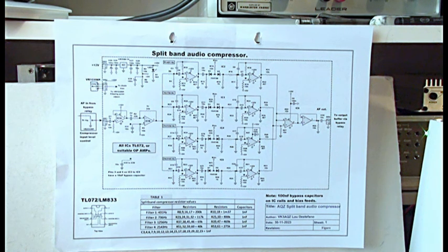The advantage of the split band compressor is that because you're filtering out harmonics that are generated inside the clipper circuits, when you recombine all of the speech waveforms, you pretty well have removed most of the harmonics, and therefore the sound should sound pretty good, as if it hasn't been compressed or hasn't been distorted. It's compressed but not distorted. It's used in some of the commercial broadcast type compressors, and it's fairly effective. Works quite well, up to about 15 decibels of compression.